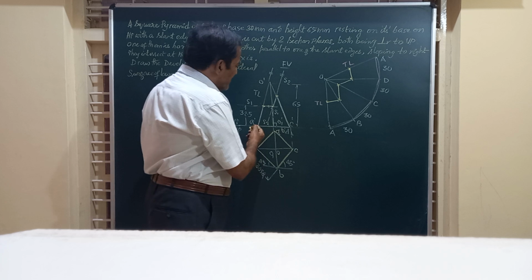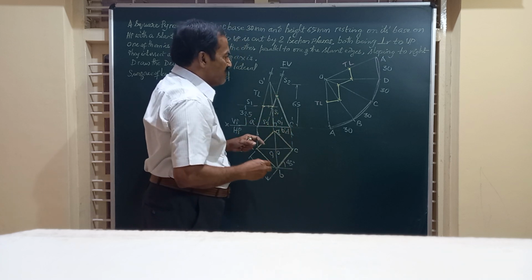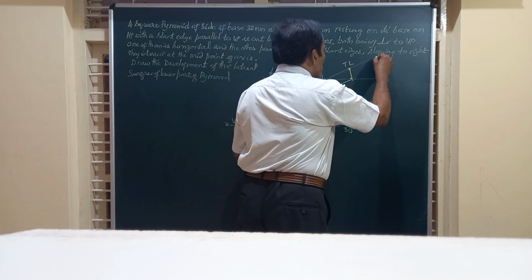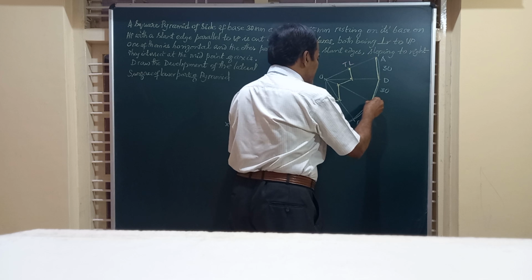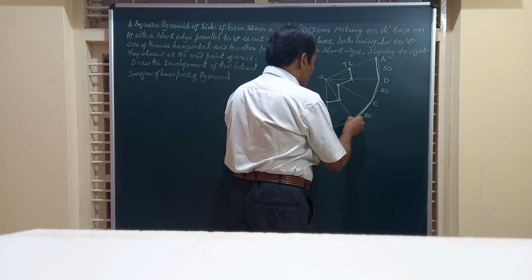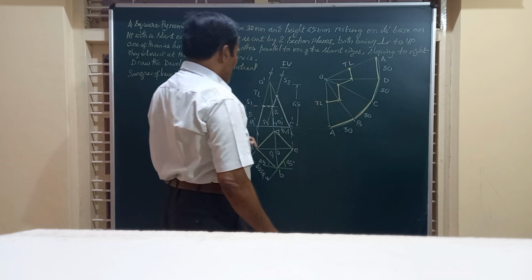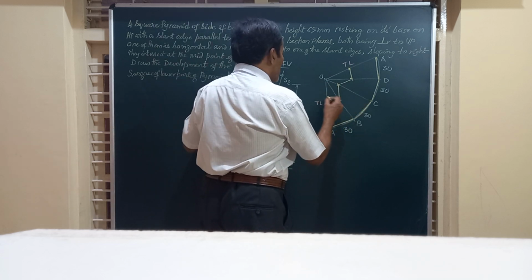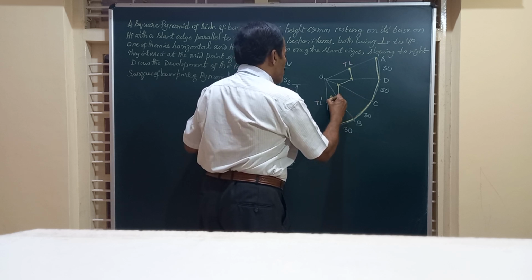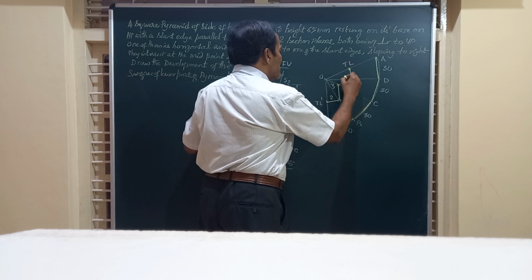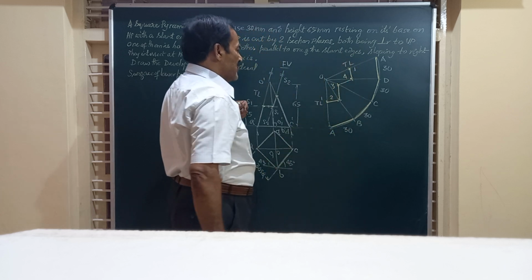And if you observe the front view, the full base is not touched by the section plane. Hence, I should show all this complete base, which are all straight edges, by straight lines. And each of these has a length of 30 millimeter. And friends, let us mark them here. I will call this point 1 on OA, 2 on OB, 3 on OC, 4 on OD, and again 1 on this OA.